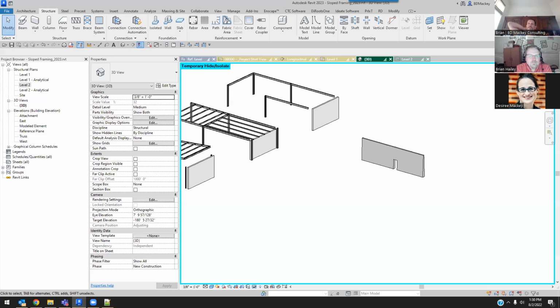Are you cleaning up registered applications? I've seen those do weird things in Revit. Oftentimes, if you're not a CAD user, you type in -pu, and then you get an option for registered applications. I literally last week went into one and deleted over 68,000 registered applications out of the DWG file. Yeah, flatten, purge, all that stuff is great, but overkill is always a good one. But the registered applications is one of the big ones I find that helps Revit, and I don't know why registered applications will do it.